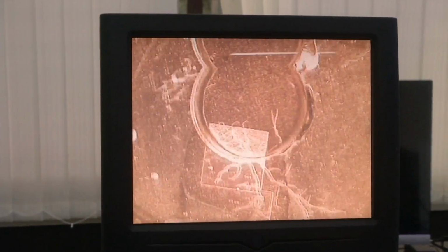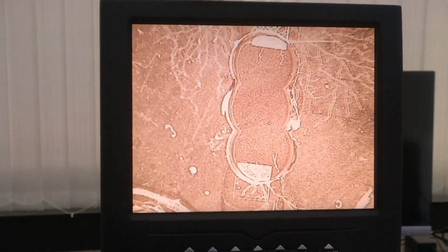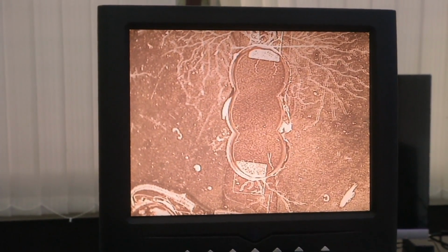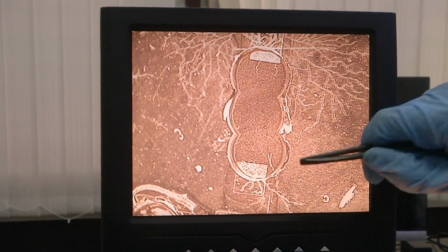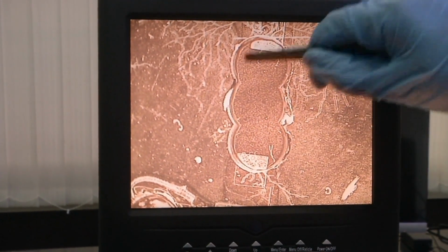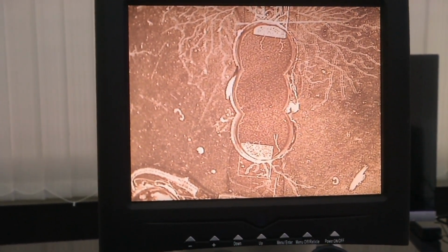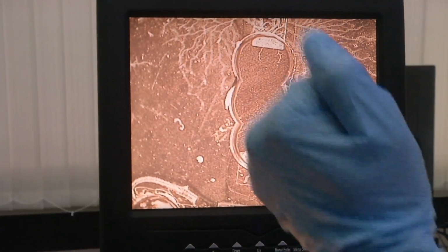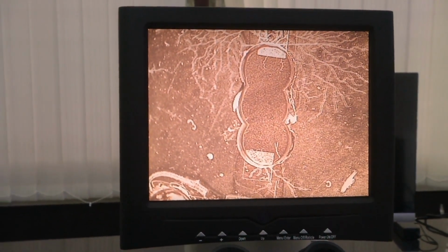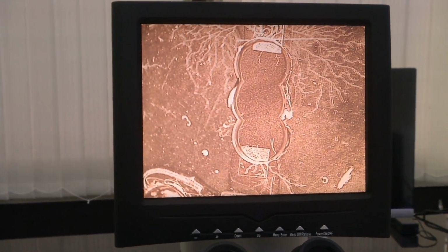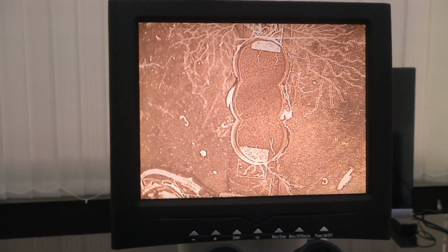So this is another well, and you can again see the material below. I am just running you through the different wells that are available. See, this is a multiple well, 3 wells have merged together. Let me just zoom out so that you can see it properly. There are two pads, here and here, and there is a bigger well, so it can accommodate more samples. For the sensor, we usually use liquid samples, say cells in liquid, or some other chemical dissolved in a solvent, that we can load on this well and see the changes in properties like impedance, capacitance, etc. That is how these sensors will be tested.